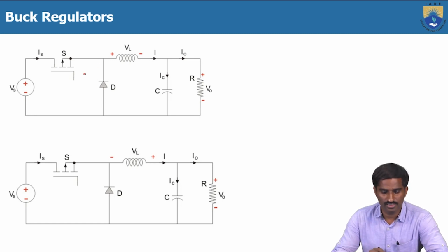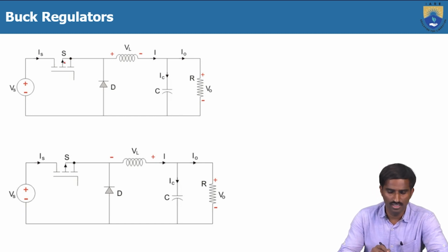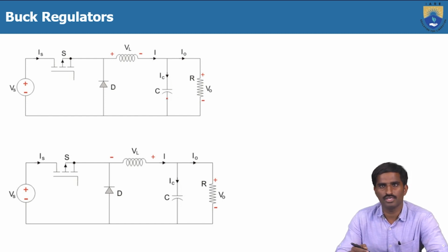This buck regulator circuit diagram is the same as the buck converter or step down converter, because it has one switch, one diode and an inductor, and the capacitor is optional, connected across the load. Here the inductor plays a major role in providing a regulated DC power supply to this load.